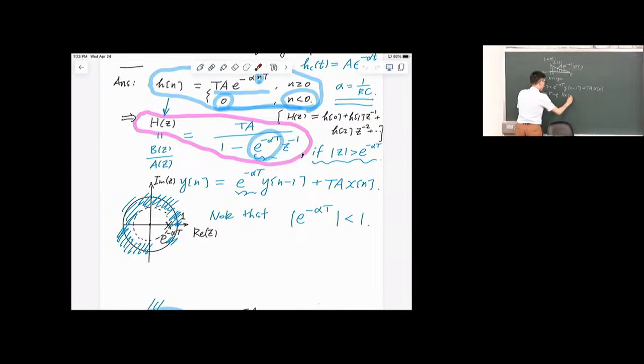Conceptually, it should become clearer and clearer that this exponential decay function really corresponds to low-pass filtering. High frequency will be rejected, and low frequency would simply be smoothed. I mean, the system performs smoothing. So for the frequency response, we expect the magnitude response to be low pass.